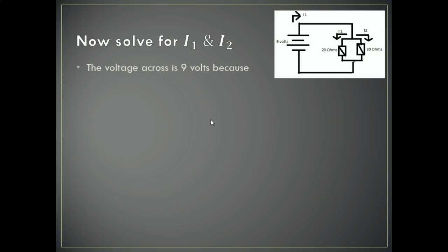We learned that because they're parallel, according to the loop rule, or remember we derived it, that parallel components have the same voltage across. Even if we did solve it, you just say that, and because the battery is 9 volts, the other side has to be 9, so they subtract to 0. So parallel components have the same voltage, and since it's only hooked up to one battery, it must be negative 9 volts here, or pretty much 9 volts, but opposite.